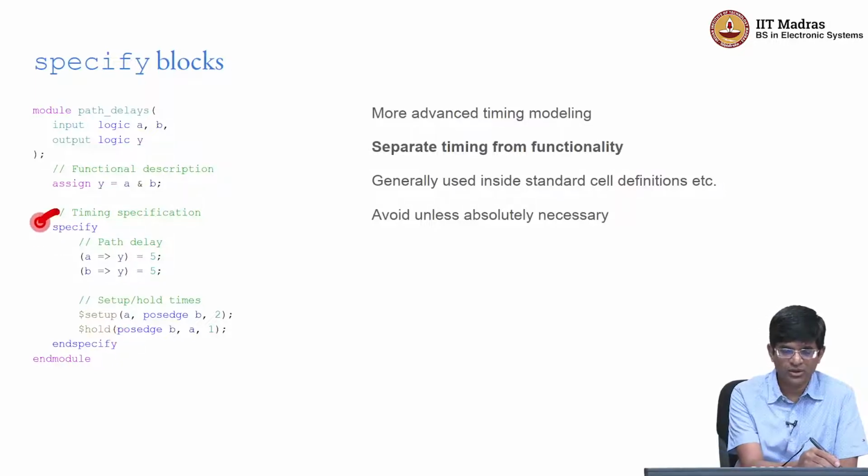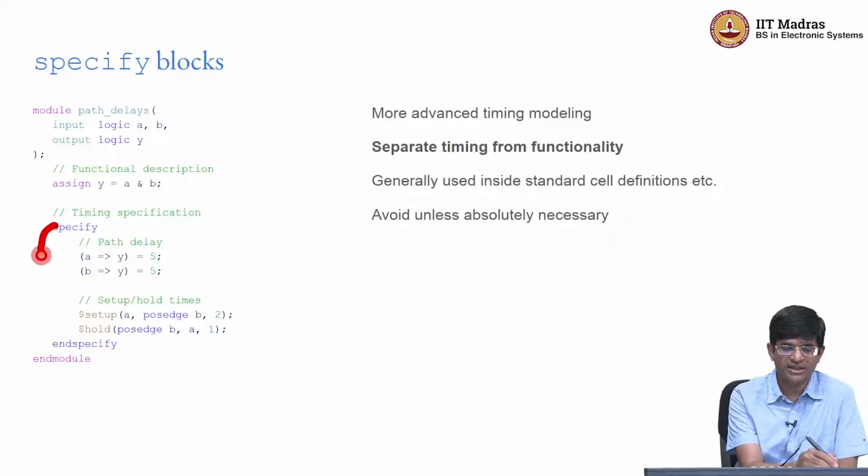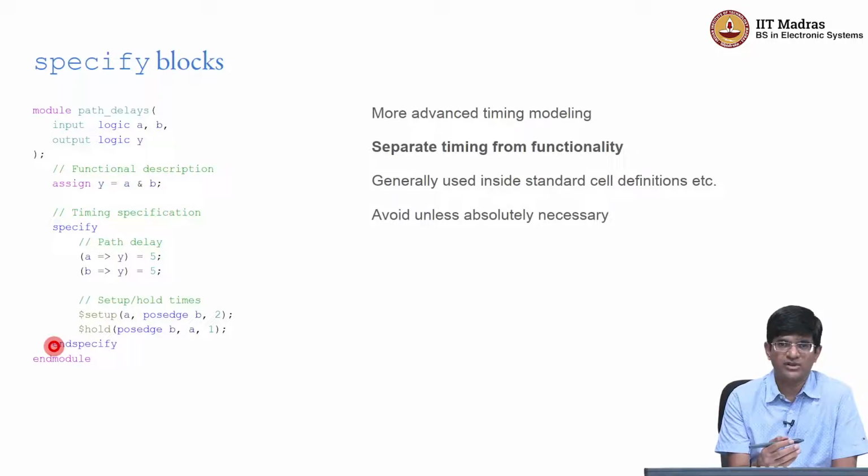The good thing is it allows you to separate out the timing specification from the actual functionality, which is very good news, because what it allows us to do is write code without worrying about timing at all. And later on, if we actually want to do a simulation that involves timing where we want to know the delays of individual gates, we can bring in that functionality using specify blocks in a completely modular manner without affecting our code at all, right. Once again, mostly this is used in the scenario where you are trying to do an actual delay based simulation of a circuit that you have already designed. You would very rarely need to go in there and implement the specify blocks yourself.